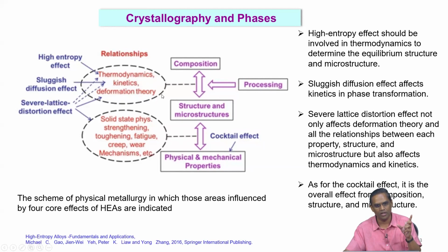This is not new to us because we have been talking about solid solution strengthening where we talk about lattice distortion, or we can deform the material by cold rolling or hot rolling. There also we are getting a distorted lattice. And then we know the benefit of all these kinds of ideas already. You know what we get out of cold rolling, what we get out of severe alloying. Superalloys have been there for the last 40-50 years. Everybody knows, hardness goes up, and when you increase the cold rolling reduction, again strength goes up, work hardening comes into play. All these things are known. But when you have multiple principal elements in the matrix, how are these effects looked at? That is the difference, right? All these ideas are known, but how they are addressed when it comes to high entropy alloys, that is the idea. So I will just show some examples which are given in this research paper.